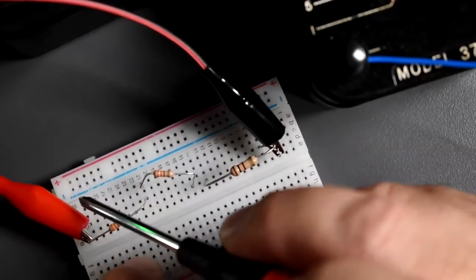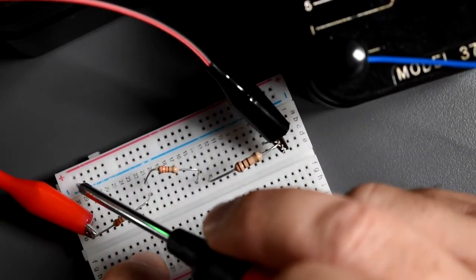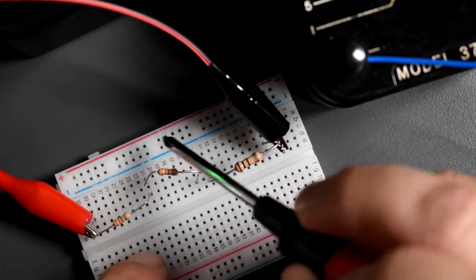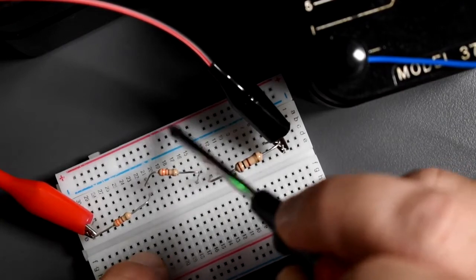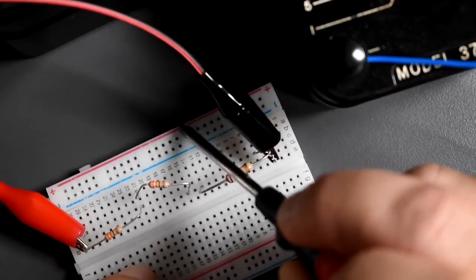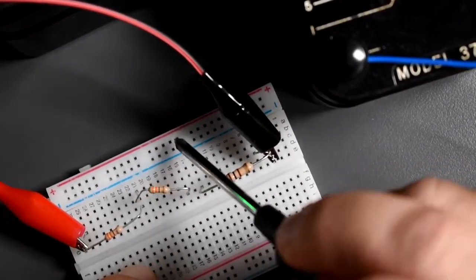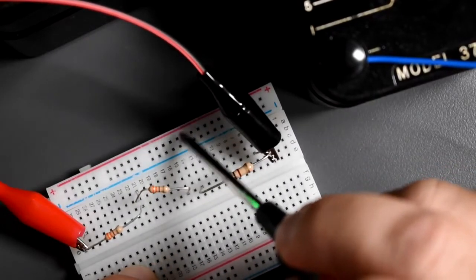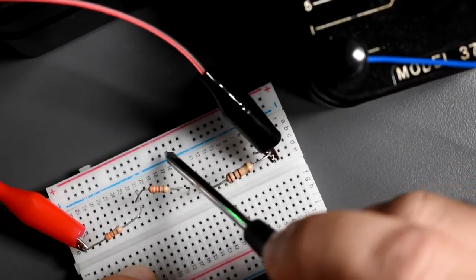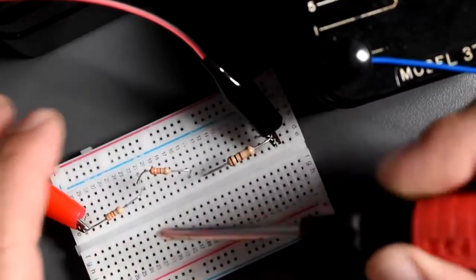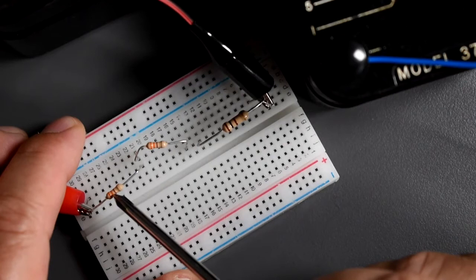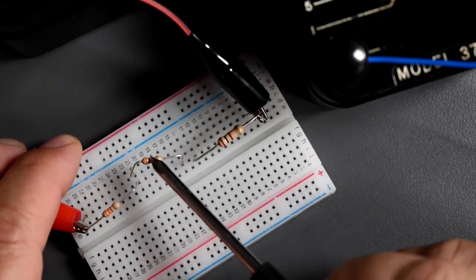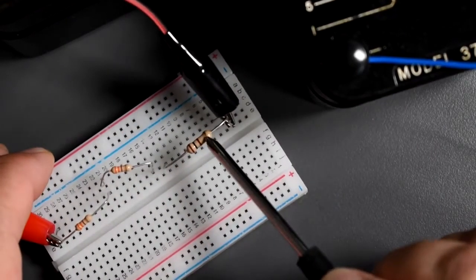Now on the top here, you've got the power rails, and they're connected horizontally. Okay? And the line indicates how they are connected. Sometimes you're going to see ones with broken lines. That means this section is disconnected from that section. So you just take a wire, stick it here, and take a wire, stick it here, and you have continuity. Okay, so this is a 330 ohm resistor, there's another 330 ohm resistor, and there's a 100 ohm resistor.